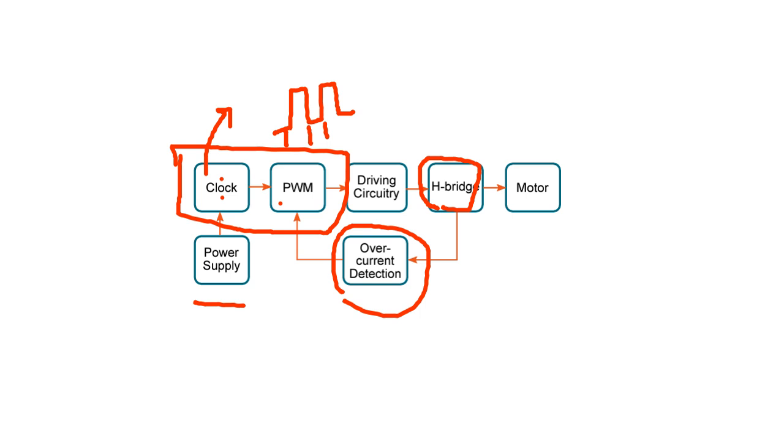This is the Hall effect current sensor. Another one is the PCB type current sensor. The cheapest one is the shunt sensor. You can use a resistor for current measurement. It's very cheap. For example, in home appliance and white goods applications, we can use shunt resistance to measure the current.